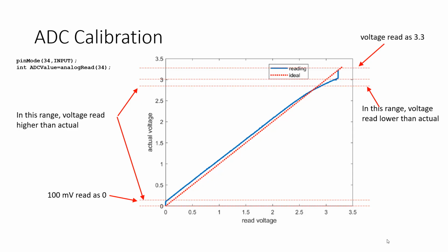So we came up with this idea that we could auto-calibrate the ADC. The way you can do that is you could take advantage of the super expensive power supplies on the benches here. These power supplies do not have the limitation that the ESP32 does.